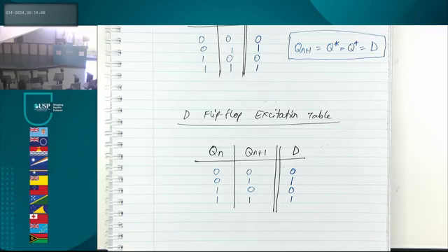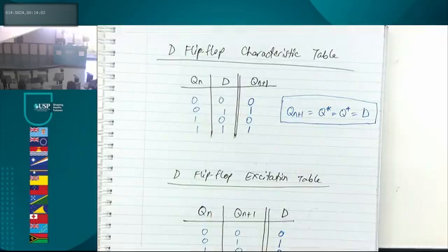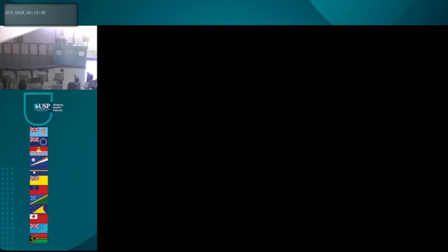All right. So, I want you to notice how this was done. We had an SR latch inside the box. We put it inside a box. Then we connected some NAND gates. We made it into an SR flip-flop. From the SR flip-flop, you got the analysis table, truth table, characteristic table, excitation table. Then we put in one more thing to correct that 1, 1, the invalid state. We made a D flip-flop.